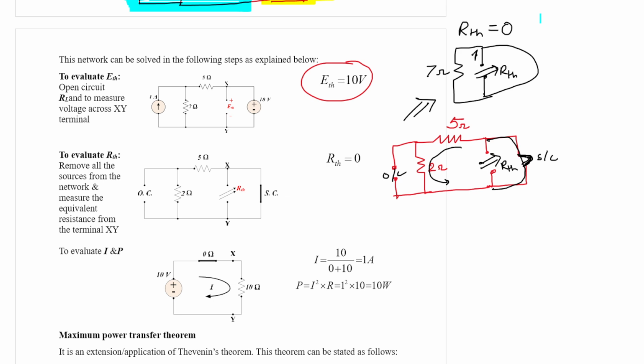One current I is being injected from this open circuit terminal. Just imagine, now it will get two paths, one along the 7 ohm resistance and another one is this short circuit path. So from the knowledge of current division rule, current will always try to flow through the minimum resistance path. So this entire amount of current I will be flowing through the short circuit path.